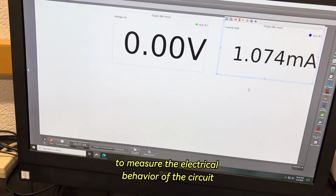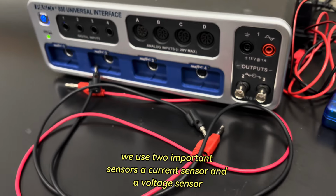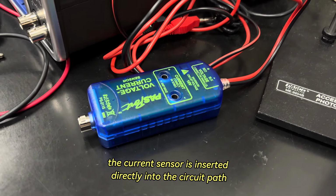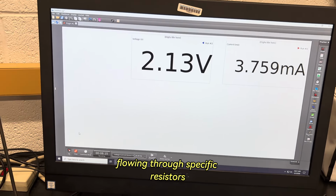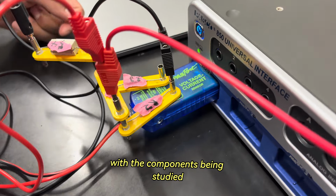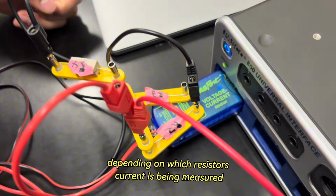To measure the electrical behavior of the circuit, we use 2 important sensors, a current sensor and a voltage sensor. The current sensor is inserted directly into the circuit path in order to measure the amount of electric current flowing through specific resistors. Since current must be measured in series with the components being studied, the sensor is placed at different points of the circuit depending on which resistor's current is being measured.